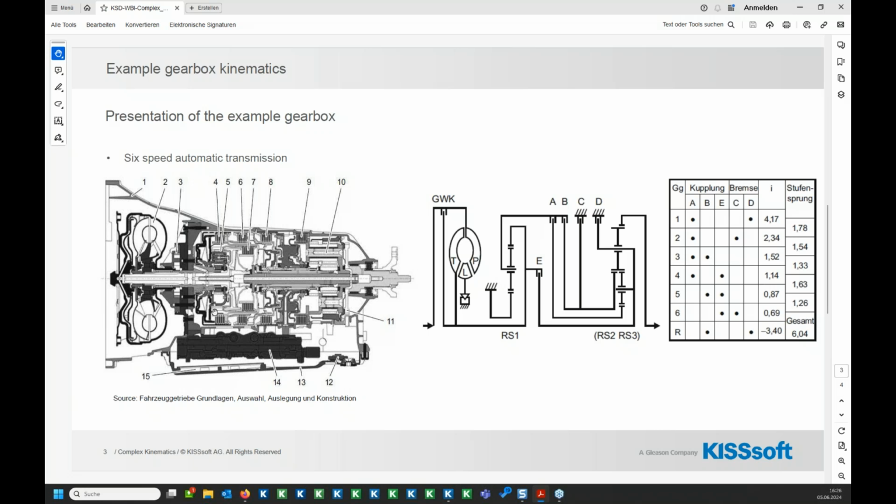It has a normal planetary stage here, where the sun is stationary and the input is from the ring. And then there are some clutches which can be active or inactive. For example, here there is clutch A, B, which connects the carrier with the first sun of the Ravigneaux set. That's the second special epicyclic stage in this example, a Ravigneaux set with sun, planet, planet, and planet ring mesh.